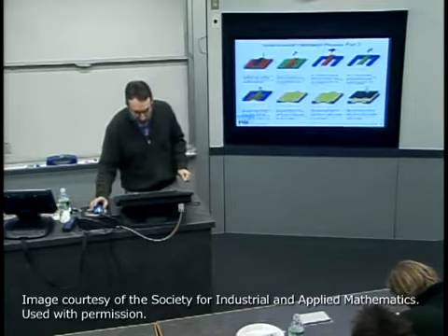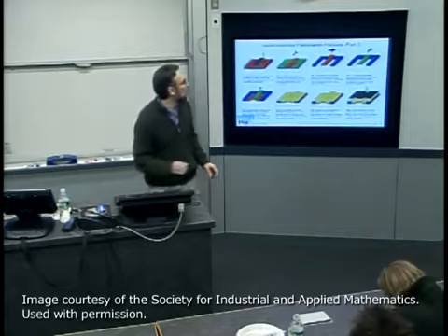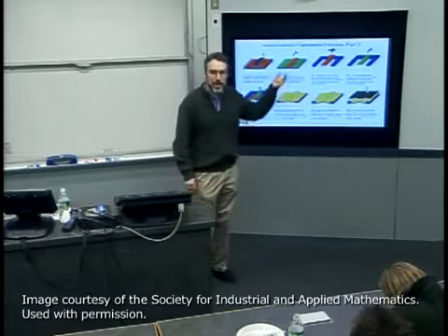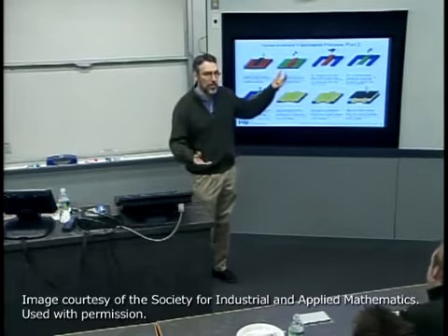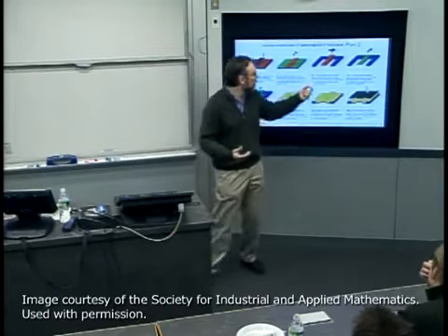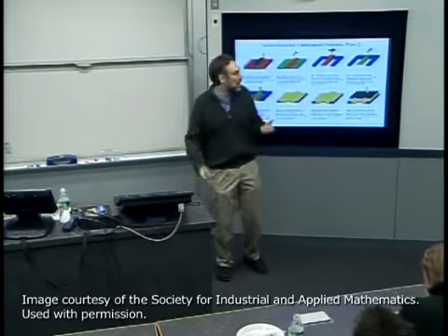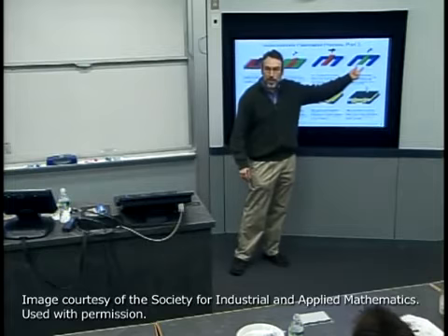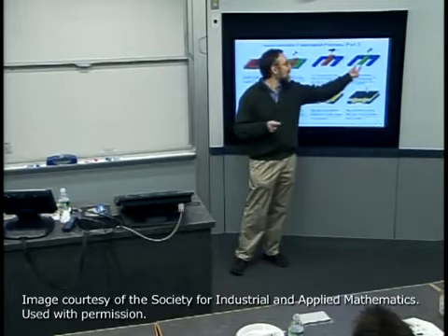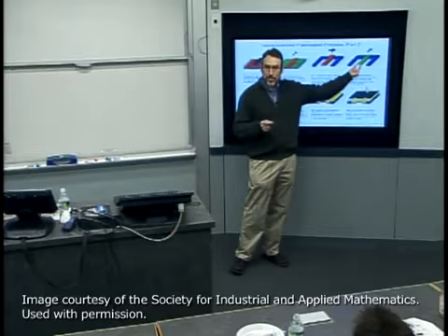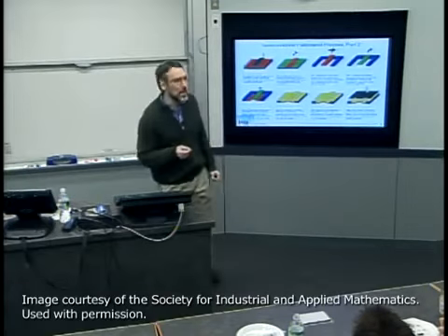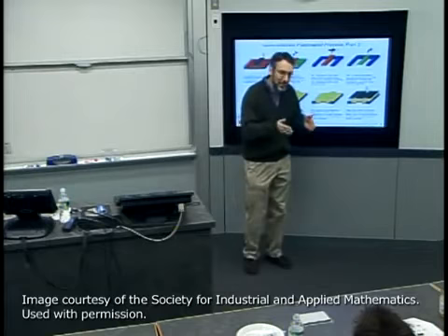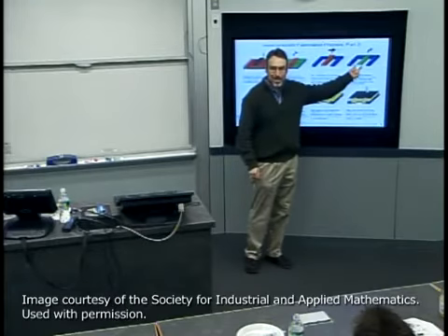In modern technology, in fact, that is perhaps the smallest lateral dimension that is determinative of the generation of the technology and the performance and characteristics of the technology. So if we talk about a 65 nanometer technology, they're talking typically about that channel length, that minimum feature size, being 65 nanometers. Okay. In fact, often tricks are played where photolithographically, using the exposure, that's the dimension that they